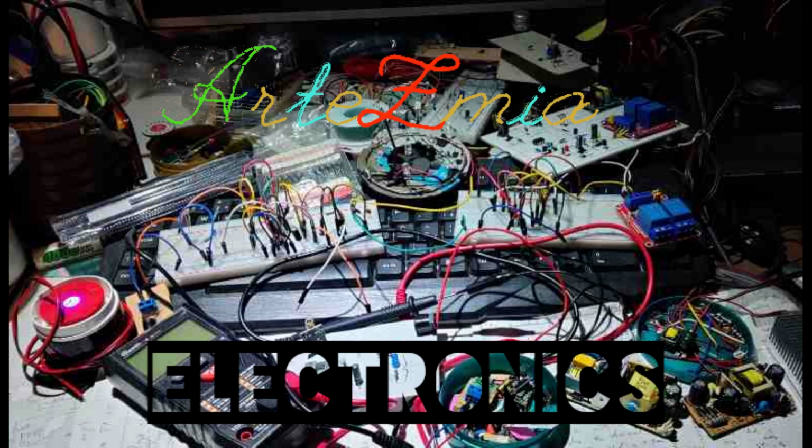Conclusion: this experiment showed that our code from the IDF 4.3.3 was successfully ported to IDF 5.0, with the exception that we had to add include rom/gpio.h to our main.c file. This was a very simple code though. There are some breaking changes between old and new versions of the ESP-IDF, especially with Bluetooth and networking. If your old code used these functions, you might have some surprises. I will find out with my tripwire alarm that I had already programmed for the S2 Mini with IDF 4.3.3. This will likely be the topic of our next video.